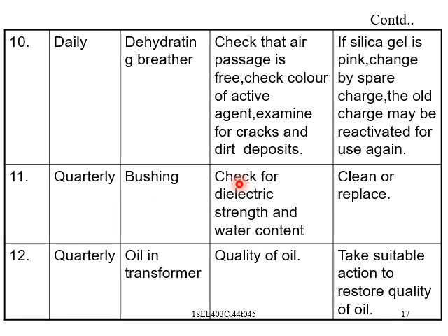Since the bushings are exposed to the atmosphere, dust, dirt or something else may get deposited, and water content also. So by that it may lose its dielectric strength. The action to be done is to clean the surfaces, or if huge damage or breakage occurs, you need to replace it with a newer one.